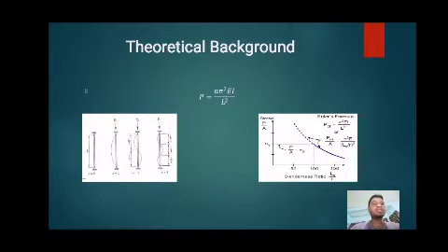The type of end connection for the column is another important factor in determining buckling stress. Based on the Euler equation, there are four types of column cases which the first picture on the left side shows. The picture shows the difference for each column as the K and L can be described from the specific condition. The moment of inertia in a column will buckle about the principal axis of the cross section.